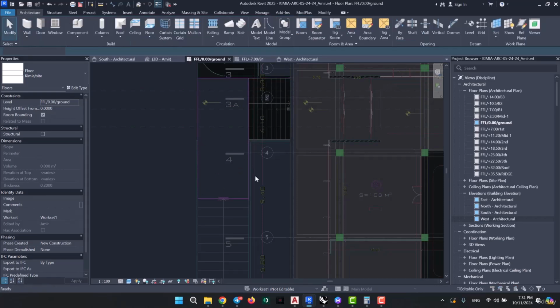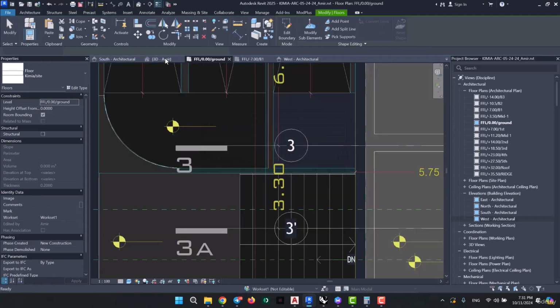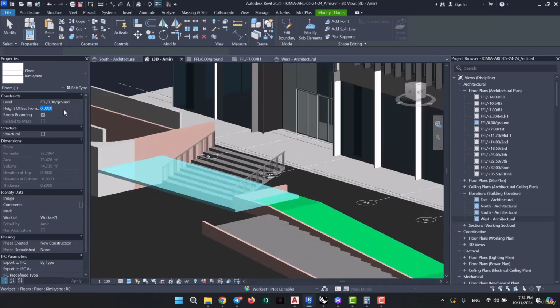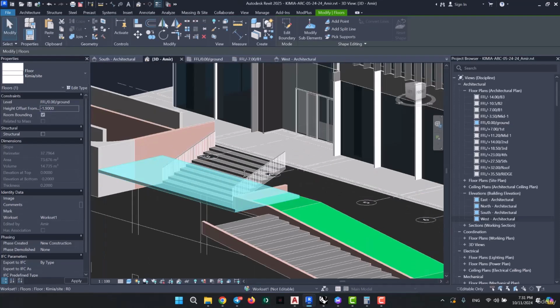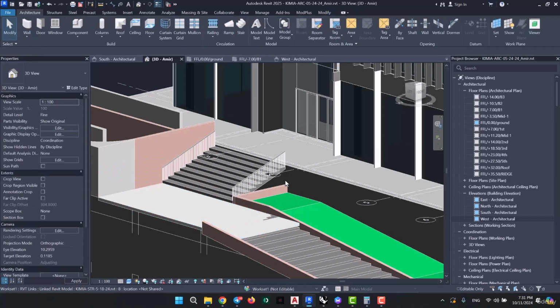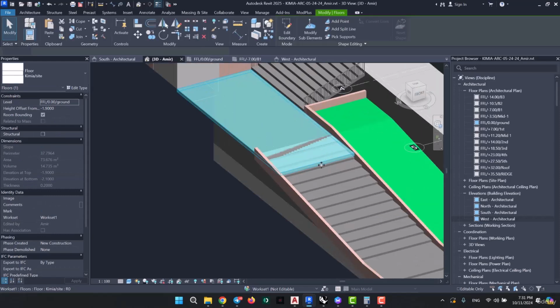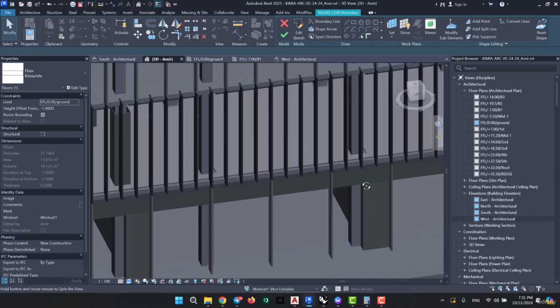And this is it. Now let's go over to the 3D view where we will readjust its offsets. It's going to have to go lower to the -1.90 offset, like so. Now because we've also added an extra stair here, you can see how the AutoCAD plan did not recognize it because according to it, the floor went to here. So I'm going to edit this floor on the spot.